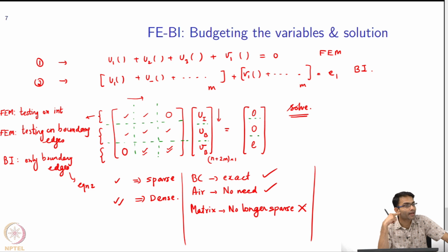But it's not as bad as if I had made the whole thing using a volume integral method, where I'd be discretizing the entire volume into one dense system of equations. So it's partly sparse, partly dense. So I need to come up with a special solver that can exploit the fact that part of the matrix is sparse and part of the matrix is dense.